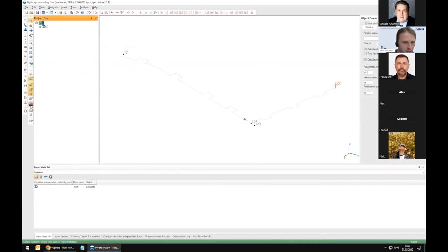Okay. So now we have this type of piping system. First of all, allow me to choose appropriate calculation methods. We have special TUFFP methods designed especially for calculating different types of two-phase gas-liquid flow, especially capable of calculating slug flow parameters. Let's, for example, say this time our fluid will flow from here to here.